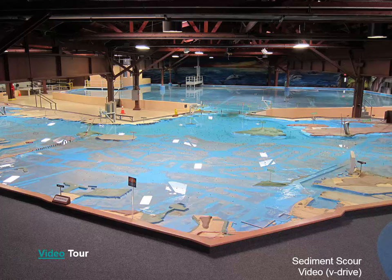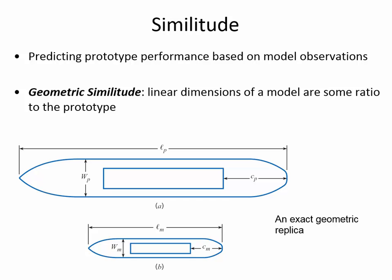And here in the UAE, they've built a lot of new things along the coast. In Dubai, for example, there's the Palm. They're making the World Islands. And those changes that they've made have affected the erosion patterns along the coast. Beaches that used to have sand that was stable, now they have to have a stockpile of sand to the side of the beach so that they can always be bringing more sand when the tides are eroding it, because they've changed the flow patterns. And so models like this can help you to understand how changes are going to affect existing coastlines, just as one example. And so modeling is very useful and important.